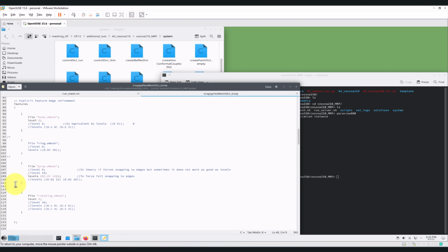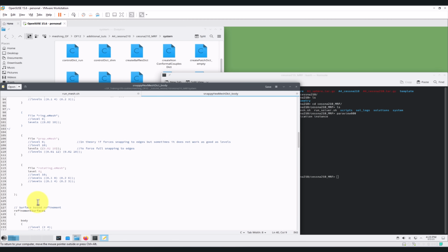The only thing that I can add here is that now that you have that cylinder, you need to enforce it in the cylinder edges, just to have a good snapping. Sometimes that can be the tricky part. Sometimes you will see that the snapping between the cylinder and the outer domain is not perfect. As usual, most of the time the solution is finer meshes. But remember that it's strongly recommended to add this snapping, otherwise you can have funky meshes. That can be a problem.